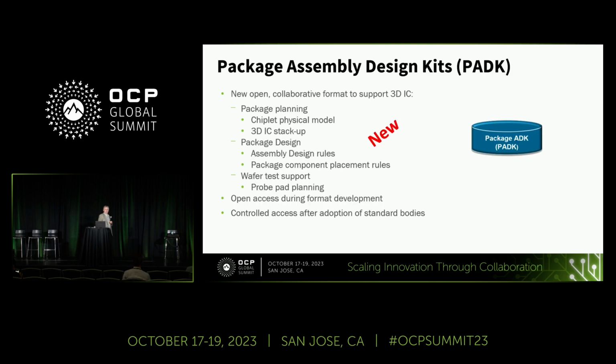Now, the next category here, we're calling it package assembly design kits, PADK. So this has three main components. One is to support the planning process, you need the physical models, and essentially the models in the CDXML, that's kind of covered, so they come with the chiplets. And then you need to define the stack-up information. This is how the chiplets get integrated into the package. So it's the XYZ placement of those objects, the orientation, whether or not they're flipped, rotated, so all of that is encompassed in what I call 3D IC stack.